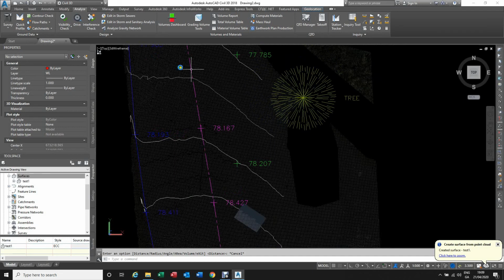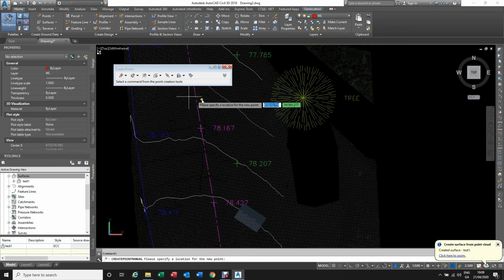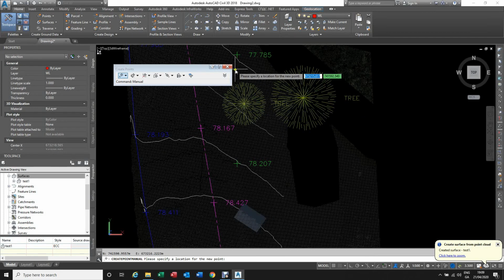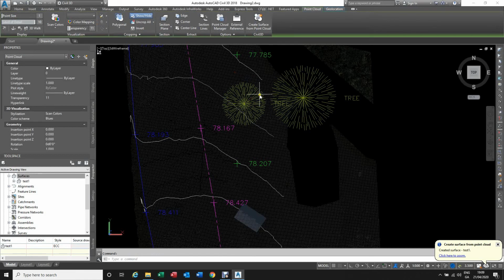You just type the code on the point creation tool here. Enter point descriptions. The same thing you would do in the field. Let's say that's a tree space 2 meter, and elevation, let's say 0 because we don't know, then it's just there. Of course it's on 0 elevation, but just for showing how it's working.